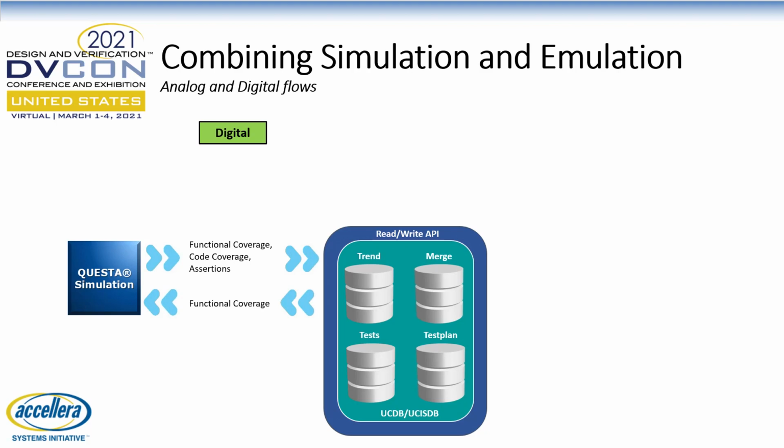But one of the cool things is that we can actually look at the functional coverage results during compilation and elaboration to optimize the simulation to ignore covergroups and coverpoints that we've already covered, so you get a more efficient simulation to target the remaining coverage holes.